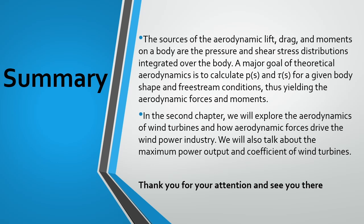So as a summary, the sources of aerodynamic lift, drag, and moments on a body are the pressure and shear stress distributions integrated over the body. A major goal of theoretical aerodynamics is to calculate the pressure and the shear stress for a given body shape and free stream conditions that yield the aerodynamic force and moments.